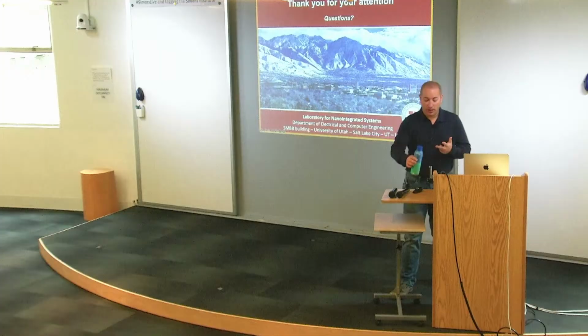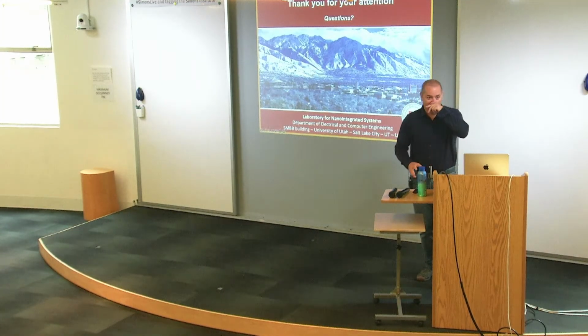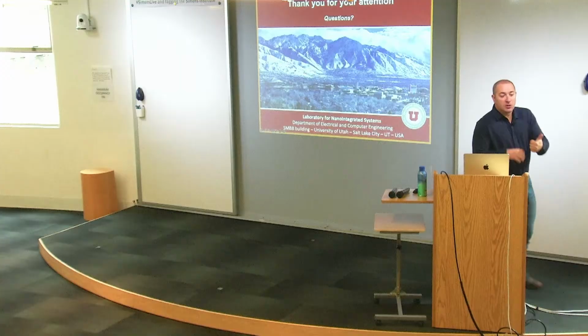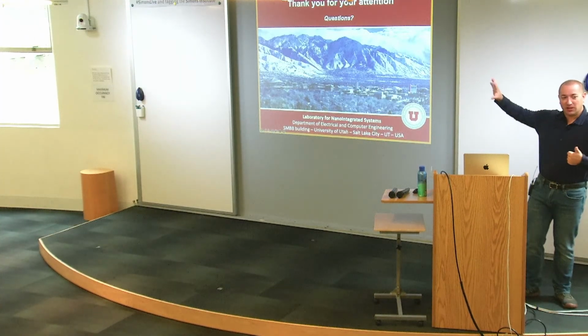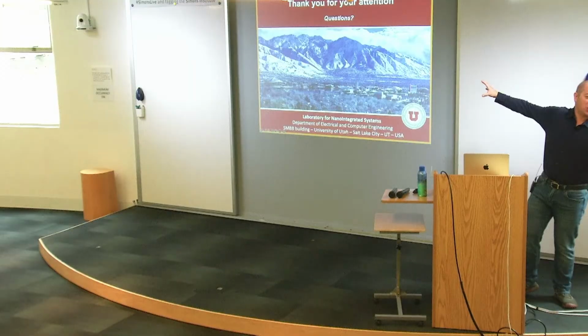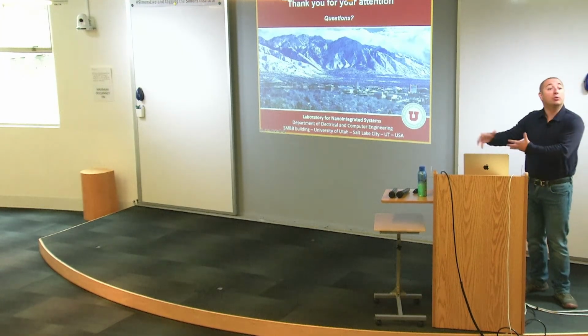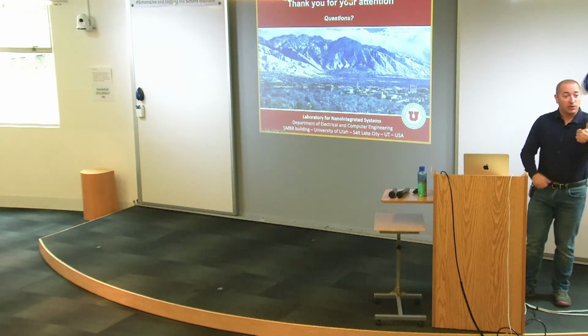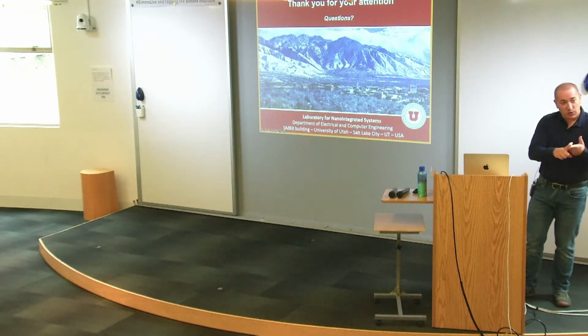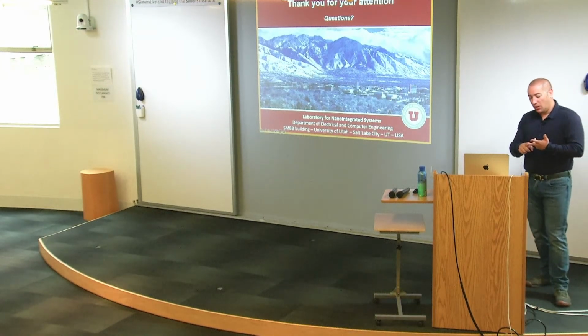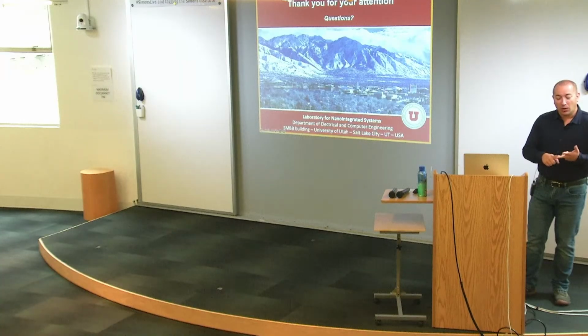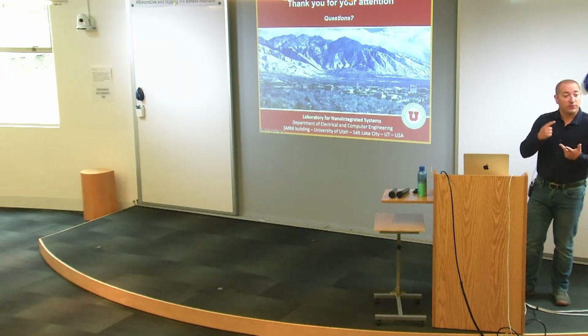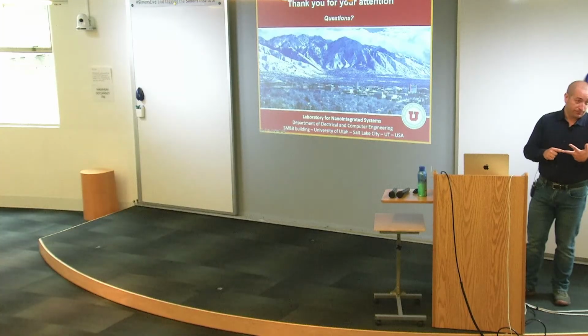So you're essentially worried about three things, right? That will be the number of gates. So I'm talking gates, right? What I showed you was mostly a graph representation. After your graph representation, you need to tech map that into gates, right? But let's talk about gates. Number of gates, because that will be linked to area. Depth of your logic pipelines, so in between flip-flops, because that will be linked to delay and performance. And to some extent, switching activity of your individual nets, because that will be linked to power.